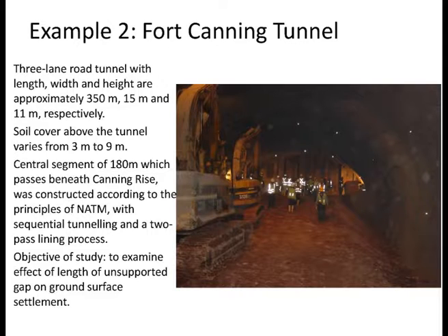My first question is this. Your thing is so shallow, why don't you just do an excavation? It is very good soil. It's bouldery clay. This is Fort Canning boulder bed. Bouldery clay, very stiff soil. There may be a few boulders around, but it's generally very good soil. Why don't you do an excavation?